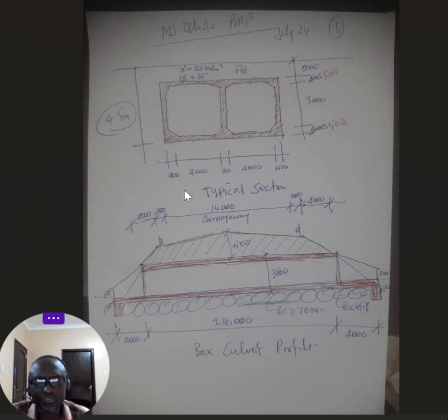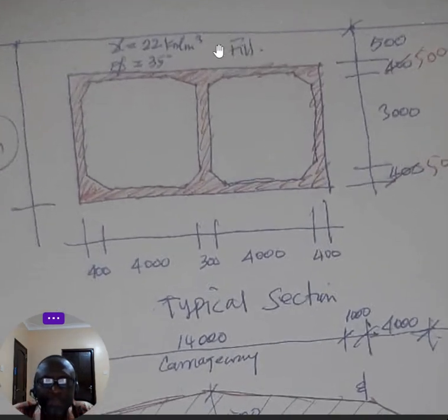And so what used to be a deep river now is shallow, and when it is raining, water is spreading everywhere. So what used to be a 20-meter span bridge, today you don't need a 20-meter span bridge. You need a slightly longer one to take on the floodplain extent that is coming out because of change in land use. So then extras like this box culvert here, I needed to add one cell to be 3.